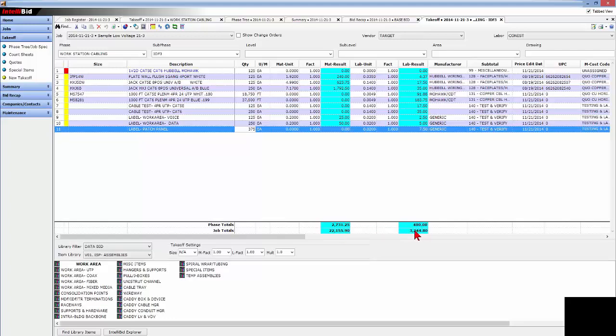Now, when a job is typically, unfortunately, starting to lose money, it's typically because the labor hours have overrun on a project. Now, these 3,240 hours, looking at the 3 floors and bidding a job like it's constructed and using your work breakdown structure, look at the job in terms of that physical construction, in terms of the difficulty in labor.